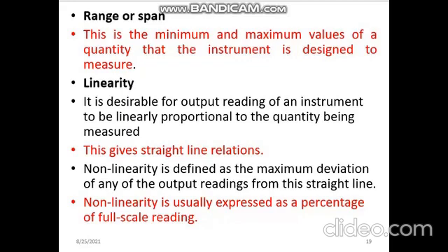And whenever you have 1 or 2 or 3 points very far away from the line, in this case you can start talking of the level of non-linearity of the system. So the maximum deviation from that straight line is what we call non-linearity. And of course, I want you to know this. If we say a system is linear in engineering, what we mean is it possesses 2 fundamental characteristics. The first one is proportionality, and the other one is what we call additivity.